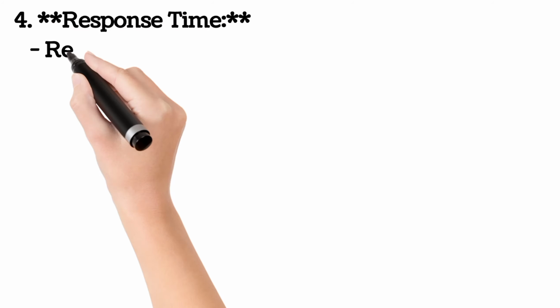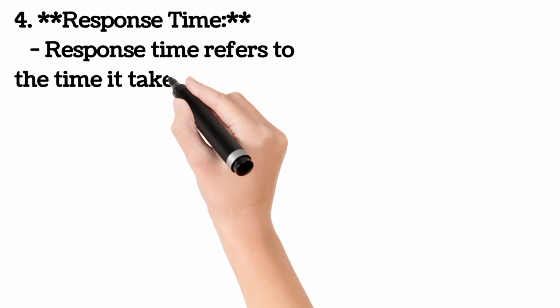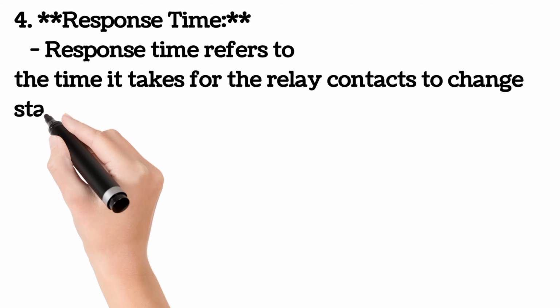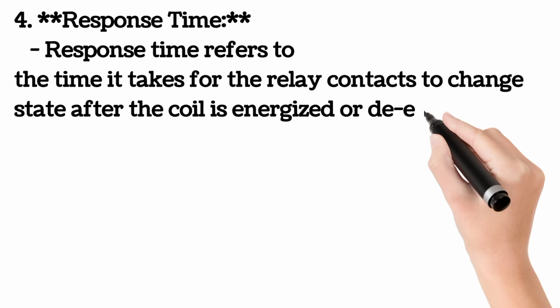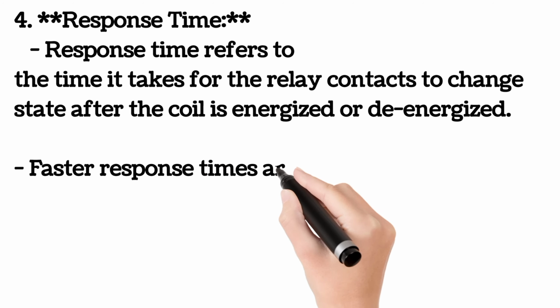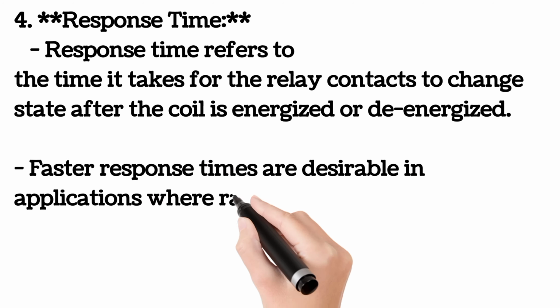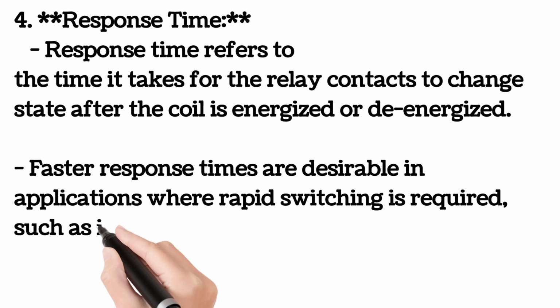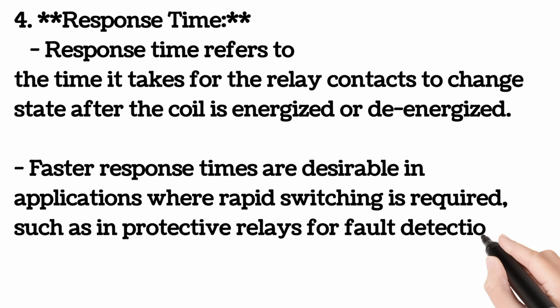4. Response time. Response time refers to the time it takes for the relay contacts to change state after the coil is energized or de-energized. Faster response times are desirable in applications where rapid switching is required, such as in protective relays for fault detection and mitigation.